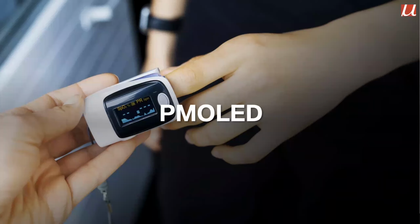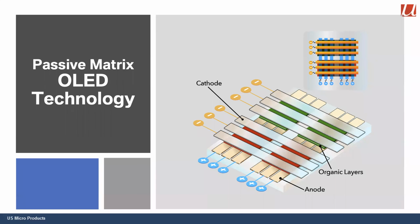So let's talk about how to build those organic LEDs into different devices. We're going to start off with what we call a PM OLED, a passive matrix organic light emitting display. And those are useful in small devices like fitness trackers and the like. The way we build these is we take a glass substrate and we lay down strips of anode material, usually indium tin oxide. And so those will form the rows of pixels in the display.